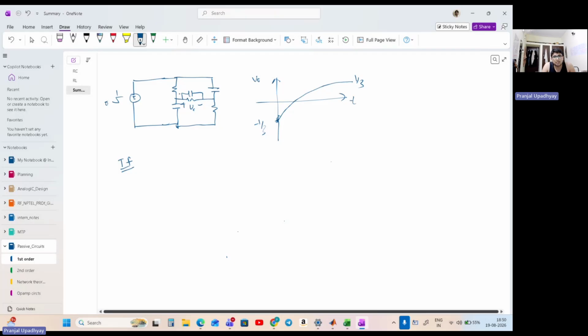But we should realize that this transfer function can be derived just as quickly and easily as we did other things. The idea here is that let us first just try to find the zero of this circuit. We know that when the zero of the circuit exists, this node voltage and this node voltage must be equal, right? Which basically means that the response of this circuit, if you can visualize, is nothing but a high pass system, and this is nothing but a low pass system.